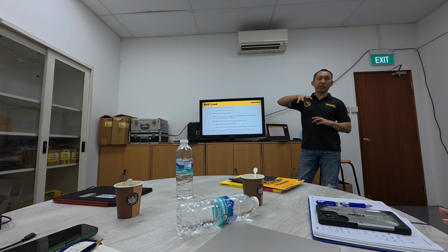So what do we mean by controlled bolting? It means the operator, the person who's using the tool and doing the job, is trained and prepared. There's a standard, there's a procedure to follow, and the amount of force is based on a calculated result. We have different tools that help to achieve this process and aid the user in providing an accurate load on the joint.